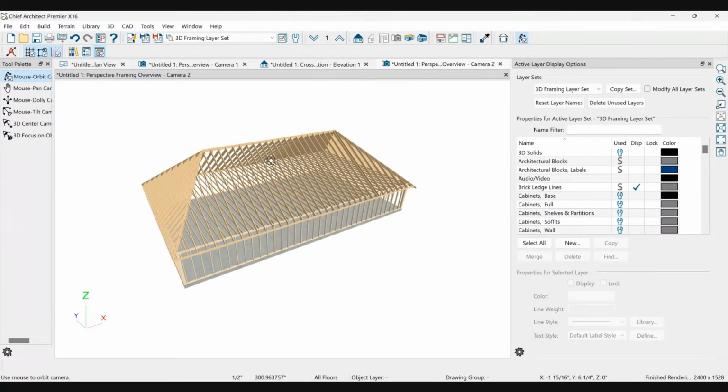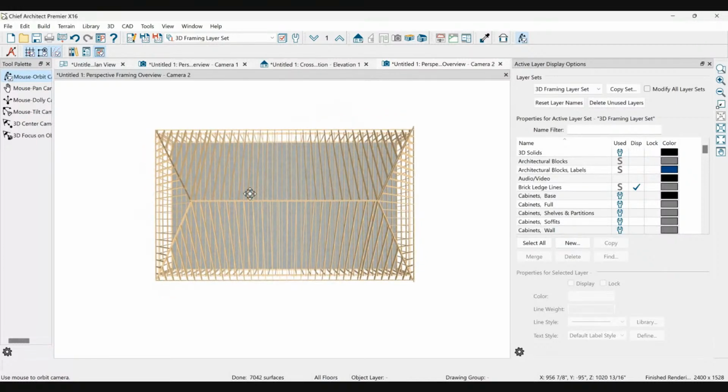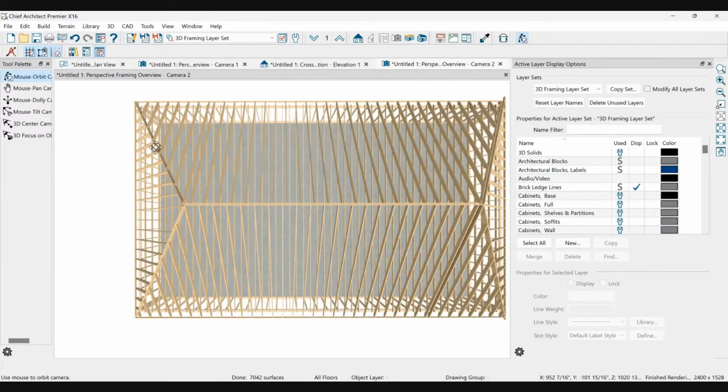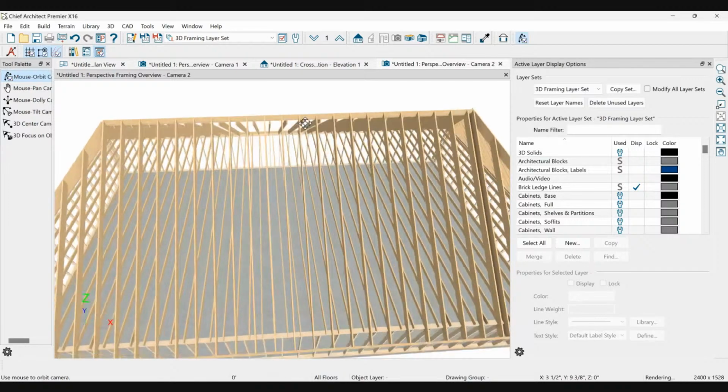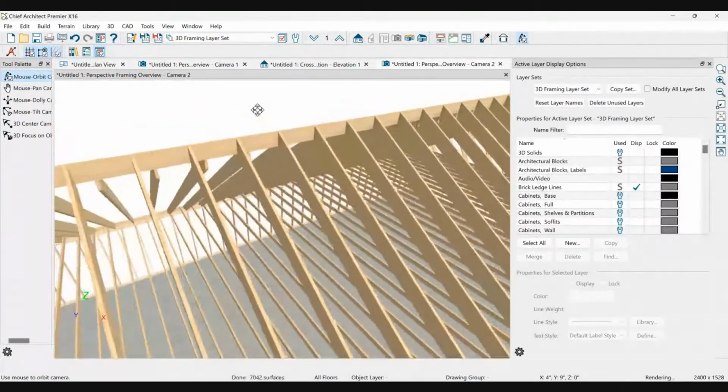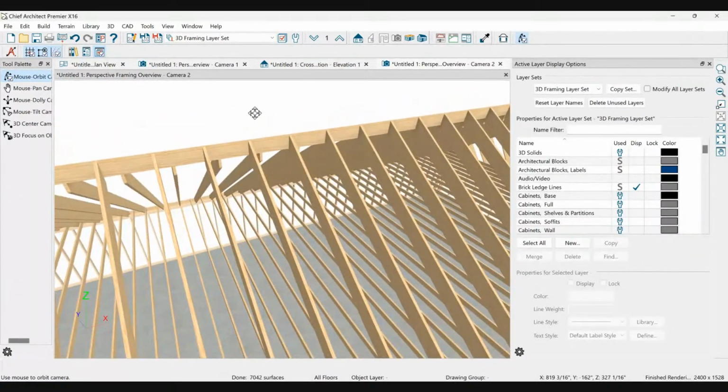In most houses, when I'm analyzing framing top-down like this, we're talking about all the bracing that we put on the hips and valleys and ridges. You need LVL as a hip or valley member when you can't brace it up. Okay, so think about this. Your ridge board up here is technically used as a small beam because you're putting braces on the ridge every 4 feet. Technically, you have little 4-foot beams holding all your rafters. That's the way to look at it.